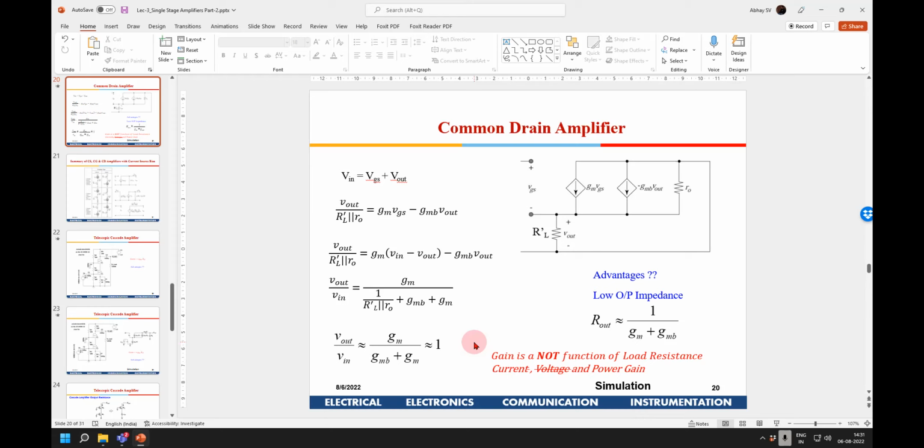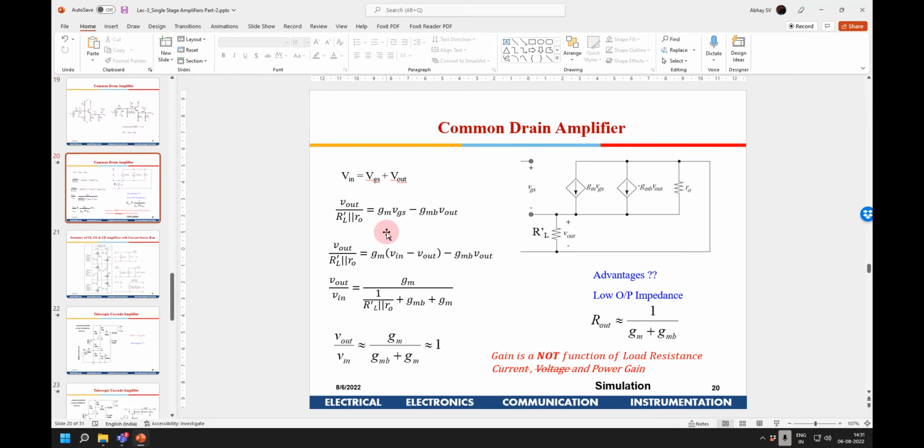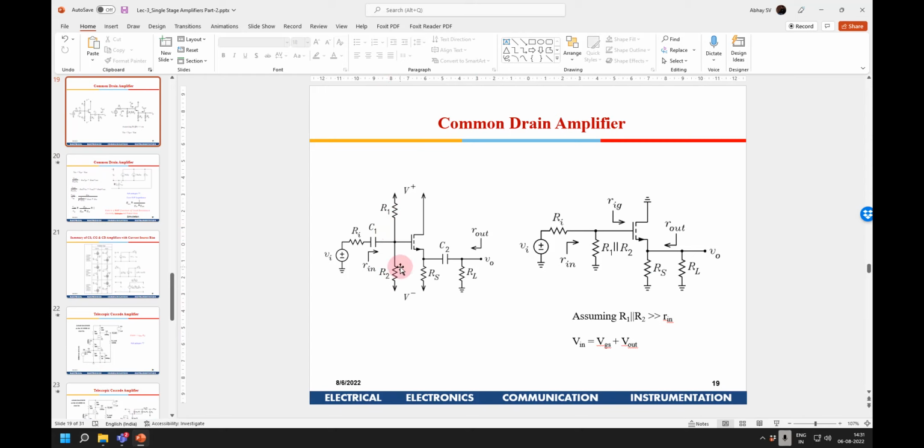Why do we really require those two resistors? To bias the circuit. For the first circuit, bias? Because we already get the output from the first stage. No. Initially, I put a blocking capacitor there, right? Now I remove that, right? Initially, if there's a capacitor out here, then to bias this, to switch it on, I require R1 and R2, right?